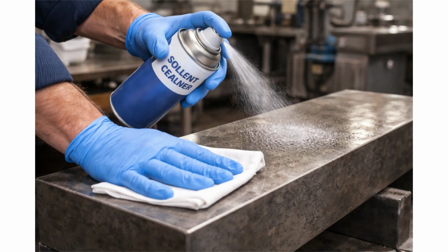Think about it: if there's oil or grease covering a crack, the penetrant can't get in. And if there's paint or rust on the surface, you might get false indications that look like defects but are actually just contamination. Cleaning methods may include solvents, alkaline cleaning steps, vapor degreasing, or media blasting. The choice depends on what kind of contamination you are dealing with.